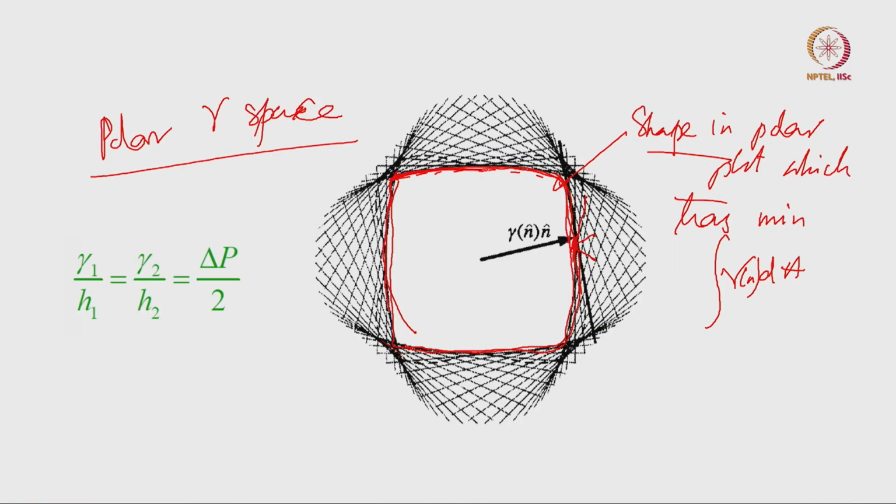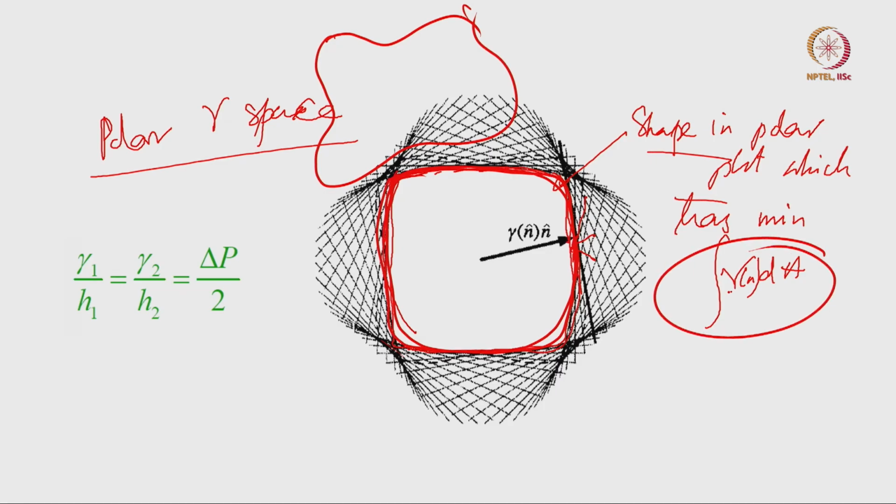So if I look at the internal envelope of all these normals, that gives me a shape. Ideally, because my surface energies are nice and not very cuspy, I also get a shape that is well rounded, not really nice facets. So here, because of this example, I get shapes which are well rounded. But essentially what I am minimizing is gamma dA.